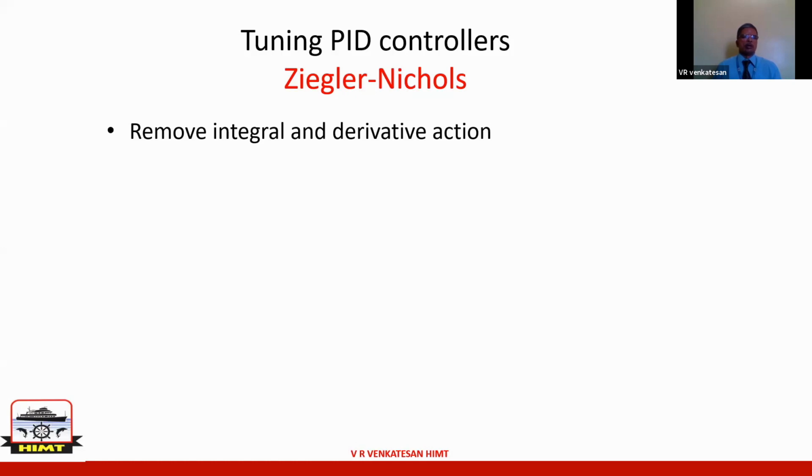Or you may also come across situations where, to overcome defects which are elsewhere, all the dials in your controllers have been turned. Just think of a simple example. In a pneumatic controller, if the output line, the line going from your controller to the actuator, has got a leak, what will be the result of this? Sluggish output. I don't have time, or I am not aware that there is a leak.